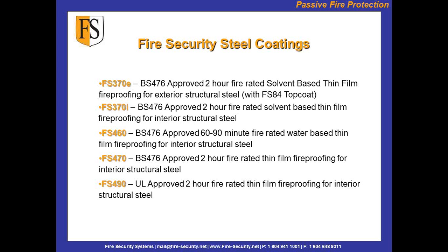So we do have an engineering letter that we can always forward out in case someone is incorporating and wants a UL approval. The film thicknesses are vastly different between British standards and UL. It's much more economical and much more cost effective to use a British standard fire curve than a UL or ASTM fire curve. And you'll see that by the film thicknesses within themselves.